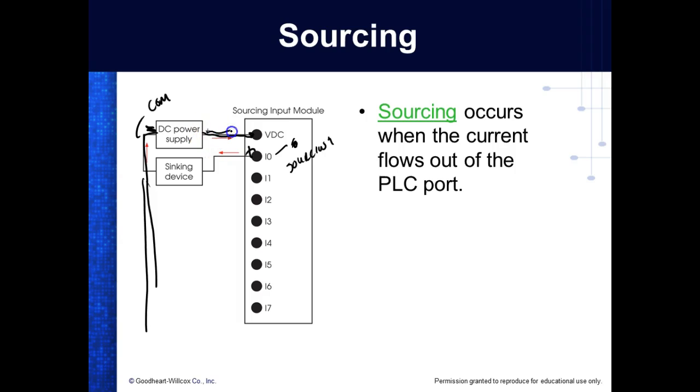So we'd hook the power supply up to the module. Now, on a modular PLC, you don't have to do this. On a fixed PLC, or these PLCs that I call hybrid PLCs, you have to hook it up. You have to take a DC power supply. A lot of these have an internal DC power supply, but most of them are not high current devices, so sometimes you have to use an external power supply. And I'll show you all that too.